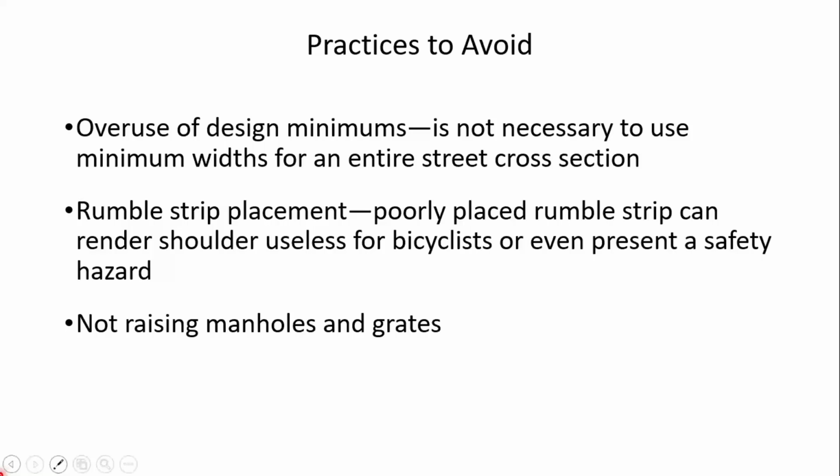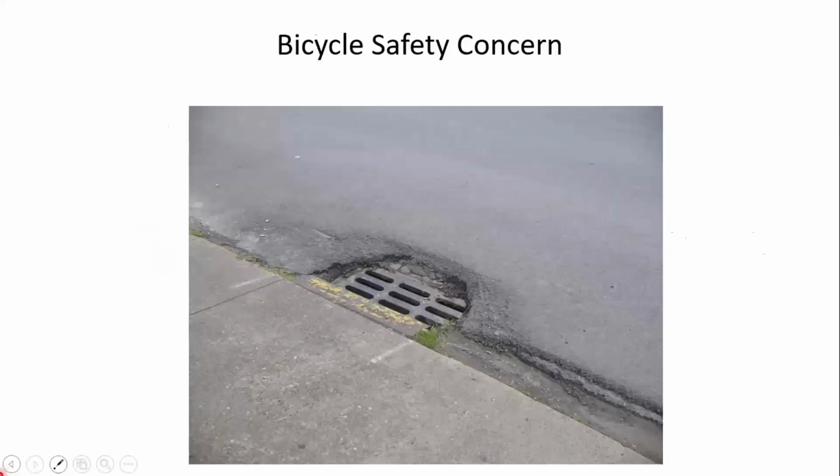Another practice to avoid is not raising manholes or grates when you're doing resurfacing operations. And here's an example of what can happen. It looks like this roadway has been overlaid at least a couple times, maybe more. The grate was not brought up or there was no milling done. And so I would argue this is a safety concern for cyclists.